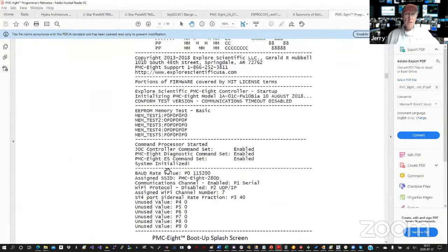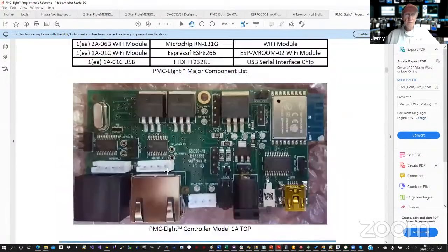So for example, let me go back here. This is what the driver chip looks like. Each motor has a driver chip, and it impacts the operation of the motor. So if you have a little bit of stuttering, or one motor working and one not, you have to understand this driver chip requires a certain voltage to drive the motor.